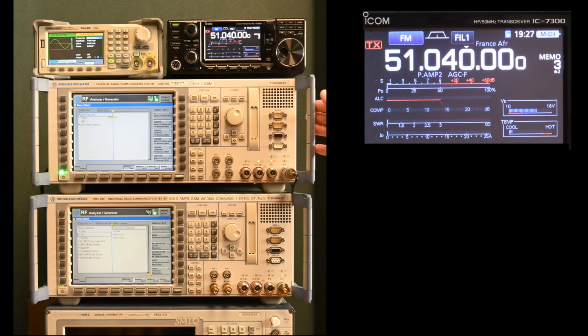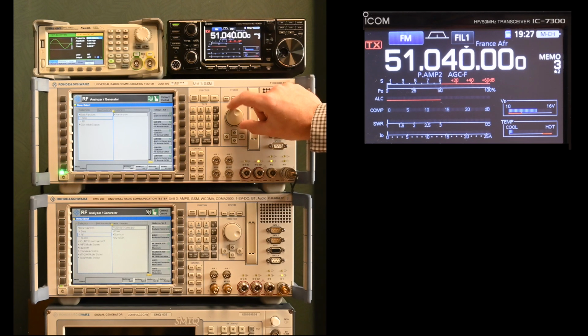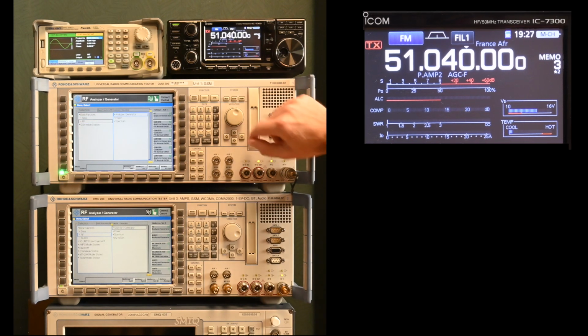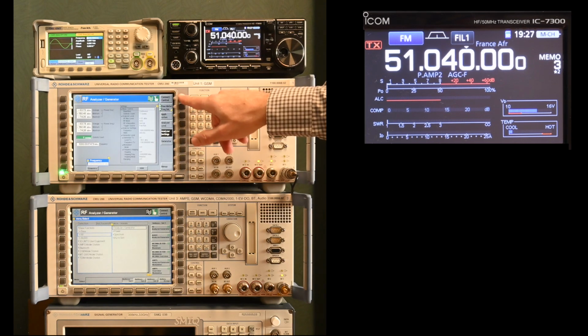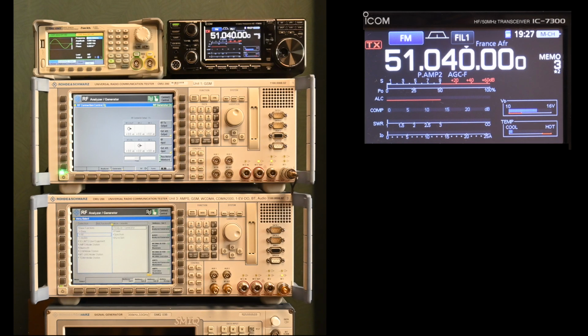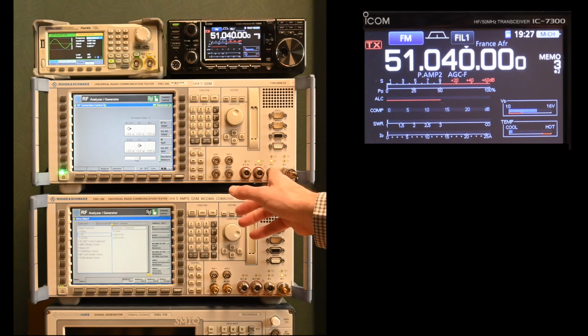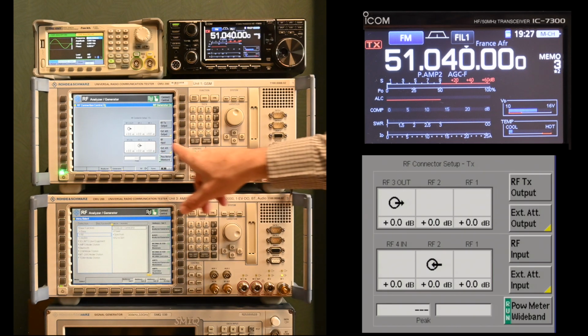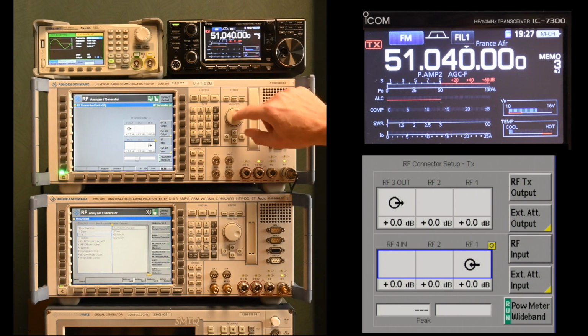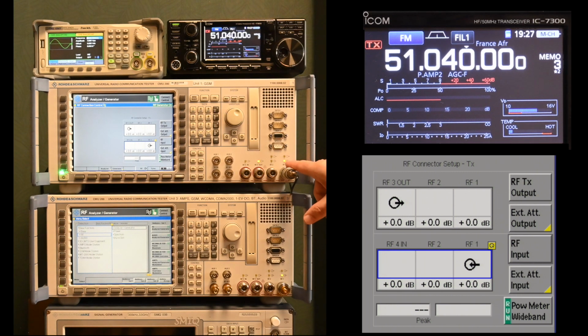Now let's go to this unit, the 51 unit, and configure it for measurement. It's in basic functions, in RF. We go here, and we get to the normal menu, and we can go to the connect control menu, where we can select the inputs and outputs. As we can see, there are little LED indicators right here. RF3 is selected for output. We're not going to use any output right now. RF2 is for input, so we have to change that. We'll make it RF1, which is actually the port that can carry the highest amount of power in this unit.